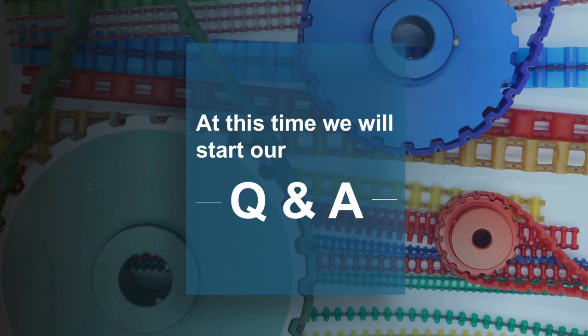Okay, Bill, thanks for that answer. Here's another question for you. Why are pulleys of lower tooth counts designated to be used as an idler only? As we discussed earlier in the webinar, there's a target amount of engagement that the belt needs to have in order to properly transmit torque and stay safely below the strength limitation of the sprocket. For Berg belts, this target is about 5 teeth.